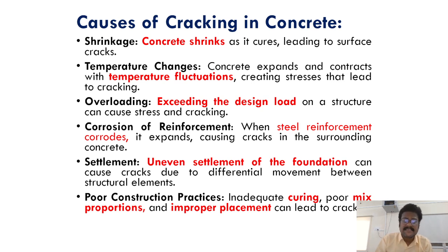The third important reason is overloading. Exceeding the design load of a structure obviously leads to cracks in that building. Then the fourth reason is corrosion of reinforcement. When steel reinforcement corrodes, it expands, causing cracks in the surrounding concrete. So, as a civil engineer, we must avoid environments which can create corrosion. Then the fifth important reason is settlement. Uneven settlement of the foundation can cause cracks.